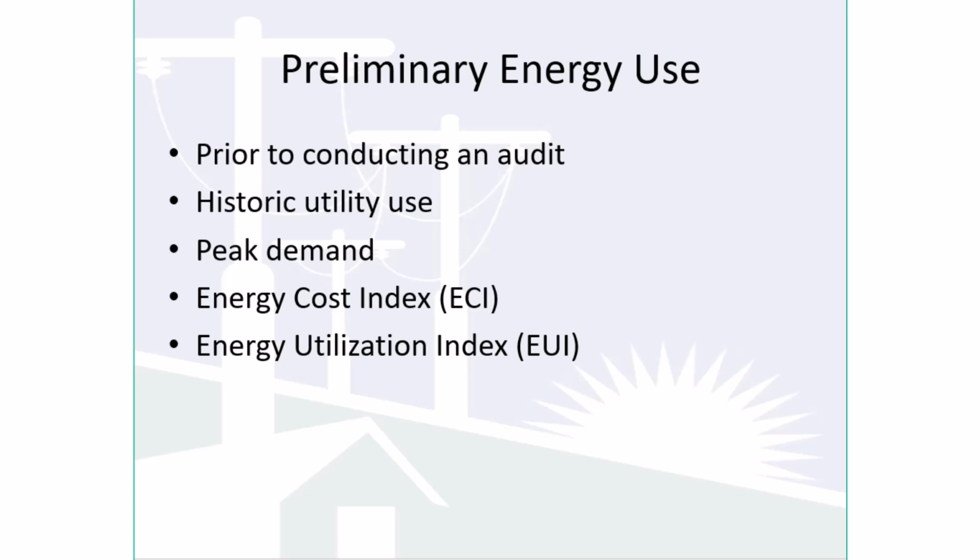Prior to doing any of the energy audits where you go on site and conduct a survey, there's one thing that is mandatory to do, and one of the most important aspects of an energy audit is the preliminary energy use. This is where we take historic utility data and we look at the energy use for each of the fuels that are used at the facility. For instance, electricity, natural gas, maybe it's propane, there could be even biofuels, whatever. And then we look also at what is the peak demand. I'll discuss more of the differences between the energy use and demand in upcoming lectures.